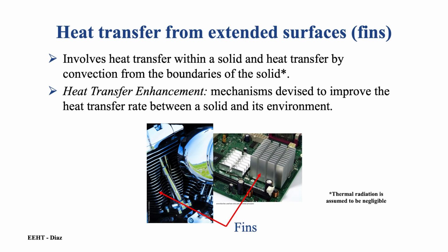In general, an extended surface refers to a geometric configuration utilized to enhance the heat transfer between a solid and a fluid. In particular, a fin is a solid of small cross-sectional area protruding from a larger surface into a fluid at a different temperature. The goal of fins is to increase the energy transfer between the solid and the surrounding fluid. In this analysis, heat transfer due to thermal radiation will be neglected.